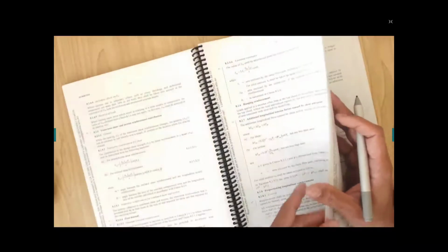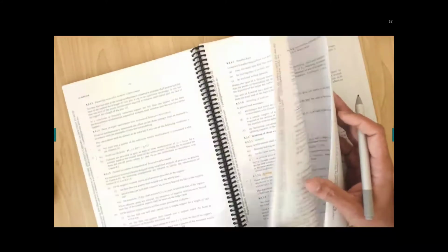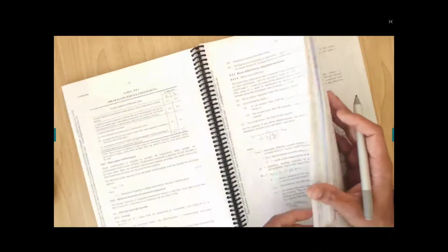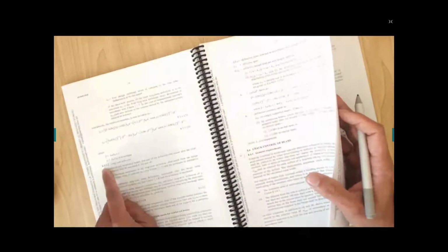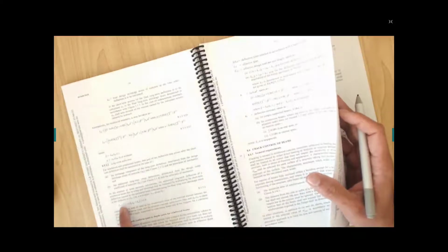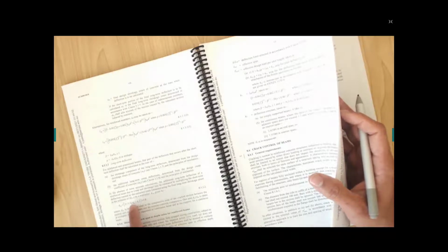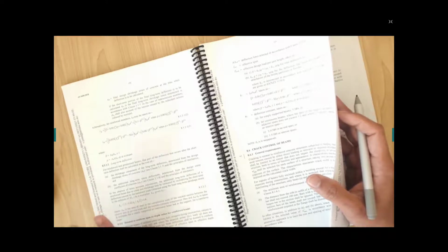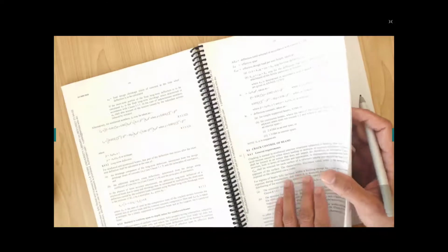We generally don't provide compression reinforcement in the slab. Generally we will have only tensile reinforcement. So k_cs, in clause 8.5.3.2, k_cs equals 2 take away 1.2 Asc over Ast, greater than or equal to 0.8. Now generally in the slab we don't provide the compression reinforcement, so compression reinforcement is 0. So 2 take away 0 is greater than 0.8, just check, it is okay. So generally speaking, in all one-way slabs or two-way slabs, we have k_cs equal to 2. The reason is we don't provide compression reinforcement in the slab.